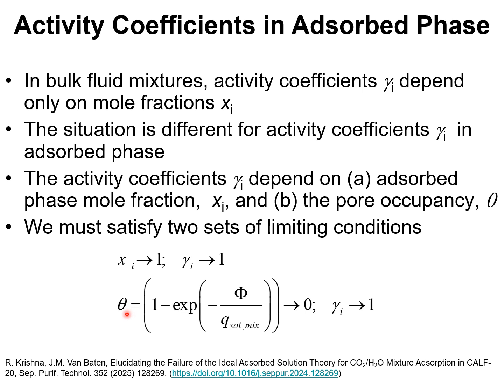Additionally, if the pore occupancy θ, which is related to the surface potential φ by this expression where Q_sat,mix is the saturation capacity of the mixture, tends to 0, the activity coefficients for all guest molecules must tend to unity.